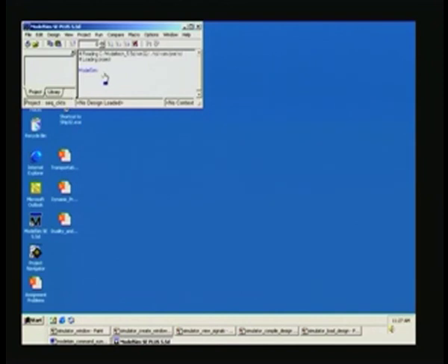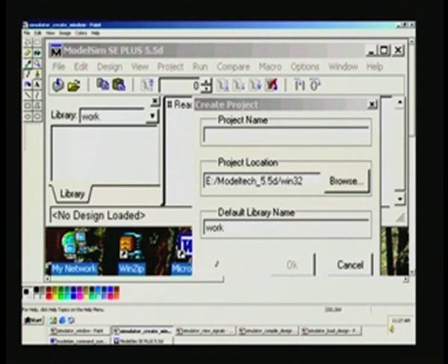So what has happened here is, you have a project here and a library here, and prior to that, what that create window was. So we will just have a look. The create window is actually this. What we had done is browse through different directories, select the directory that we wanted, and then key in sequential circuits here, and we also ensured that the default library name is work, and then pressed OK. It reported that it is already there, and that is why we asserted yes.